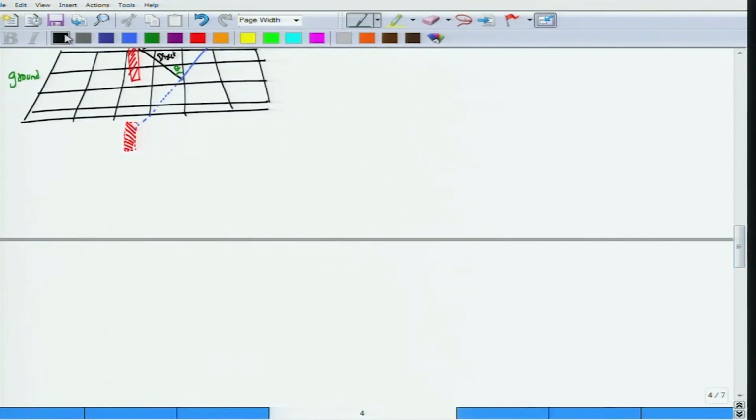All right. So we will close our discussion of characteristics of the antenna by looking at two additional factors. One of these is again related to the pattern itself. This is called antenna beam width, and as I said, antenna beam width is one of the characteristics that separates one antenna from another. For example, this is a pencil beam, then you will also have a fan beam. Obviously this antenna radiates much larger, and the width over which this radiates would be much larger than the width over which this particular one would radiate.